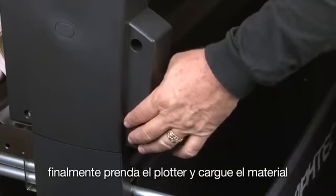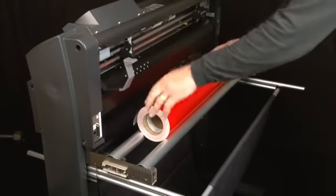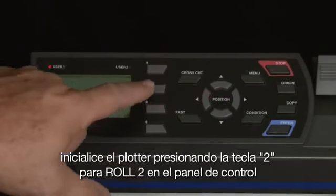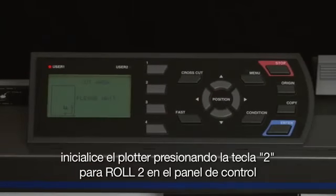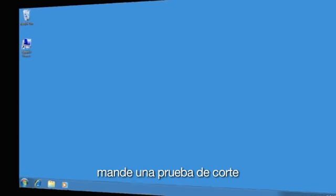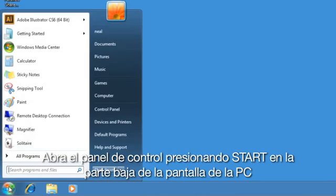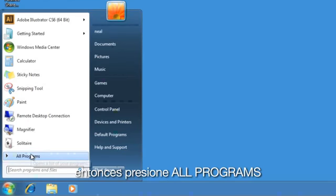Finally, turn the cutter back on and load the media. Initialize the cutter by pressing the 2 key for Roll 2 on the control panel of the cutter. To make sure that there's communication between the controller application and the cutter, let's send a test cut. Open the cutter controller by clicking on the Start button at the bottom of your PC window. Then click All Programs.